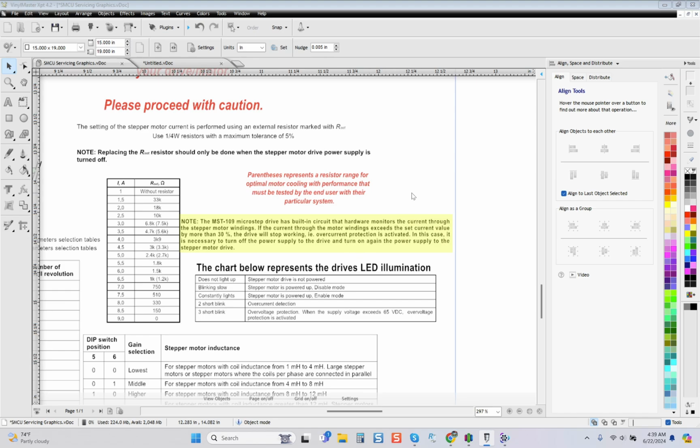So basically what you're getting told here, very simple, is that the drive is smart enough to know something's wrong, and it's letting you know by activating its overcurrent protection to, once again, stop everything so no damage is done, and it protects the system.